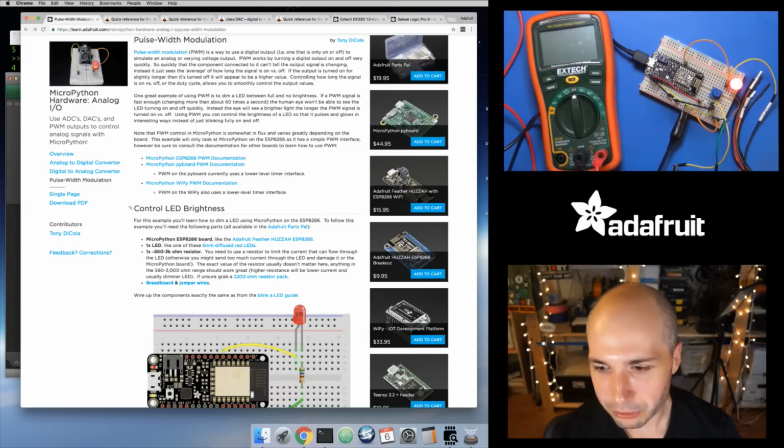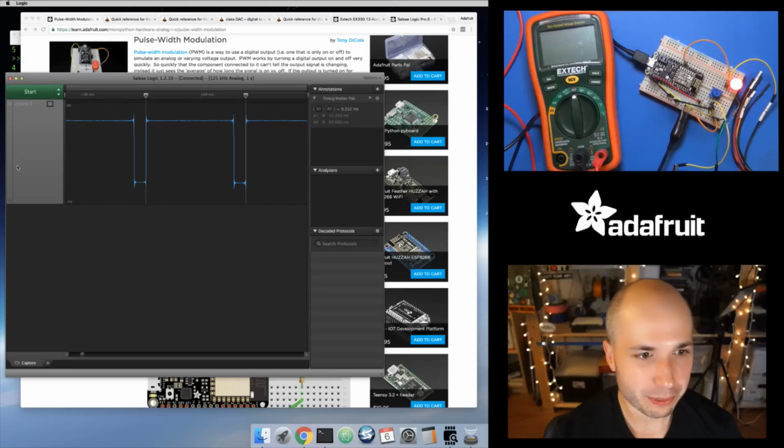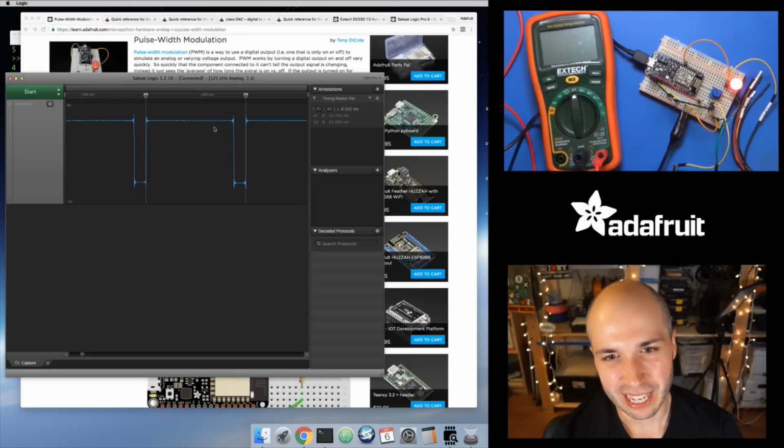So someone mentioned you might use a buzzer or something with a PWM output. Yeah, you could totally do that, because music and sound is just a value kind of like this LED. It's a continually changing on and off signal. Now you're not going to get a pretty sound if you fed something like this. This is called a square wave because it looks like a square. It's just completely on, completely off. So if you fed this into a speaker, you're basically just instantly pushing that speaker from fully extended to completely extended in the opposite direction, which can actually damage speakers. So be careful sending square waves into them.